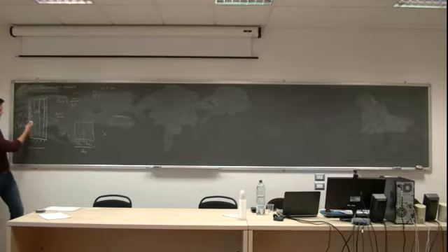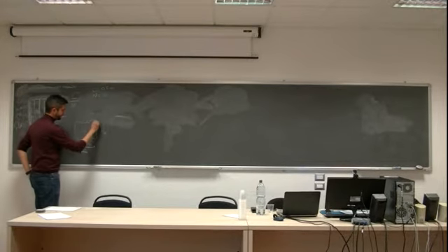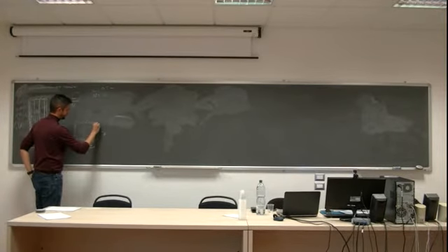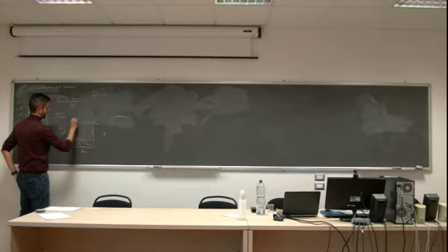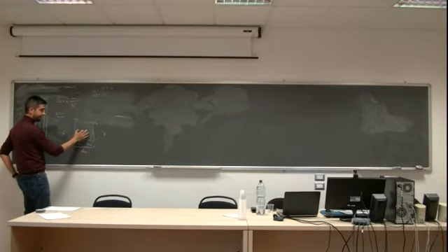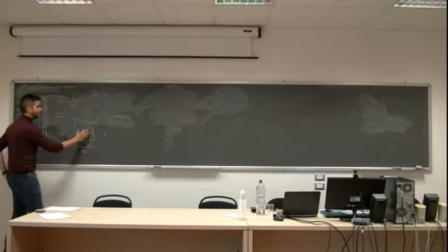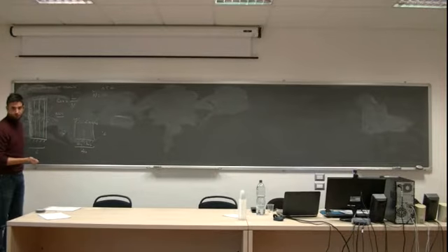Okay. Because in the case of, for example, node number 2, I will have to compute conduction from 2 to 3 and from 1 to 2, right? I will need to know the areas, SE and SW, the area that contacts the node that I am calculating now, for example number 2, with the east node and with the west node.